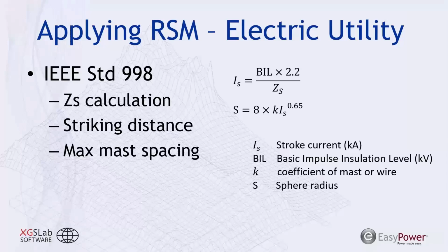It's the peak voltage that your insulation equipment is able to withstand without a flashover. Another term you may have heard of is the critical flashover. That's really a value associated with that. At a certain peak voltage, there's a 50% chance that you could have a flashover, and those are interrelated to each other.